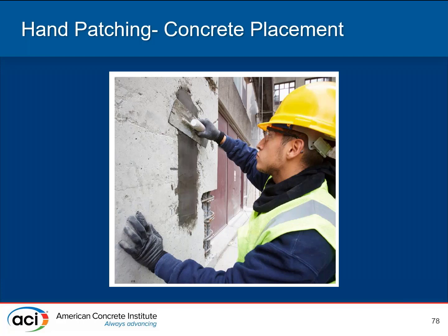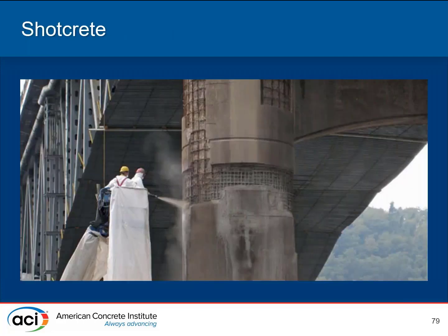Otherwise, if you're trying to do a large area, it can be fairly labor intensive, and you often run into issues with it debonding because you're relying on the worker, the mechanic, to force it into place underhand. There are specialty mortars designed to be used in this situation that have bond enhancers, but it's really only good for when you're dealing with a small area, such as what is shown in this picture.